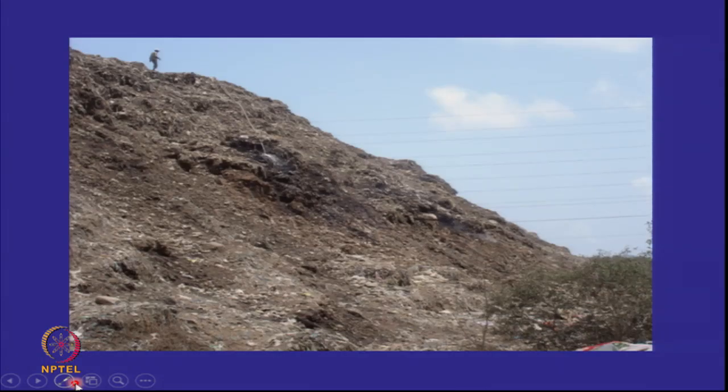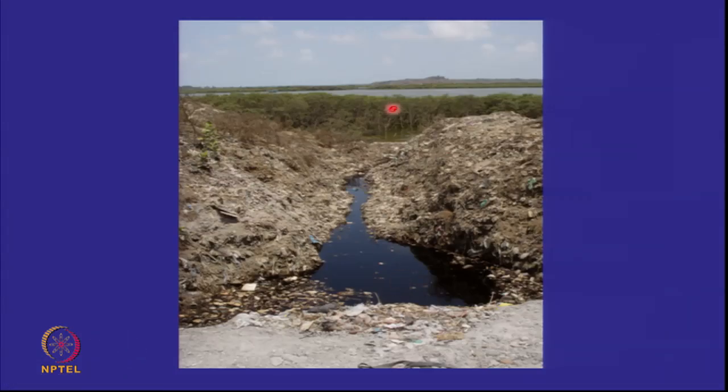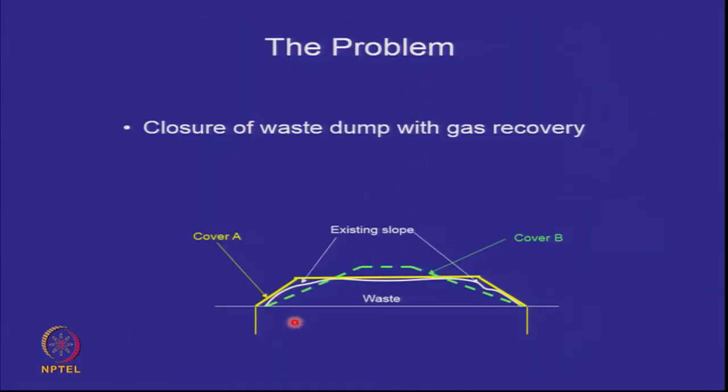But this was a quick recap. This was the landfill. I've probably shown these figures to you. That is the leachate, that is the creek. And the idea was that this waste was about 15 to 18 meters high. The slopes were very steep, and we thought we could put a cover like this. It was sitting on clay, but still some vertical cutoff walls were attempted.